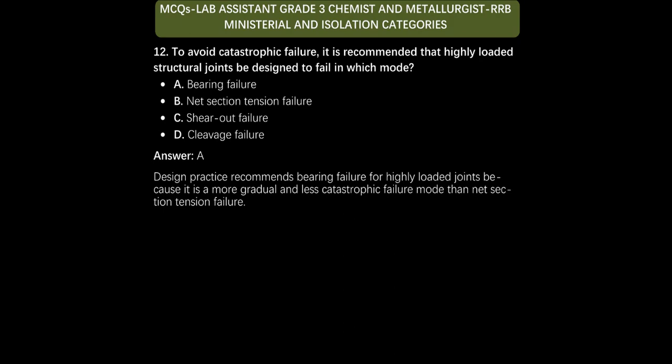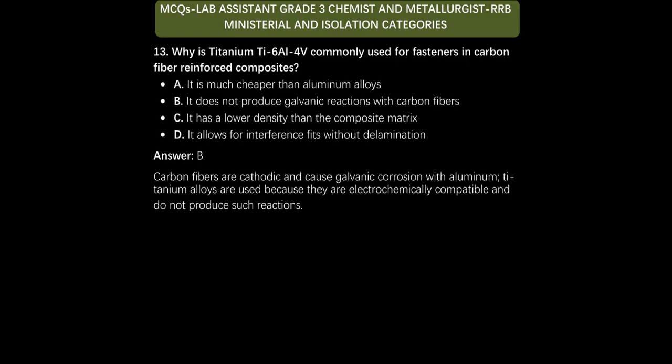To avoid catastrophic failure, it is recommended that highly loaded structural joints be designed to fail in which mode? Option A. Bearing failure. Why is titanium commonly used for fasteners in carbon fiber reinforced composites? Option B. It does not produce galvanic reactions with carbon fibers.